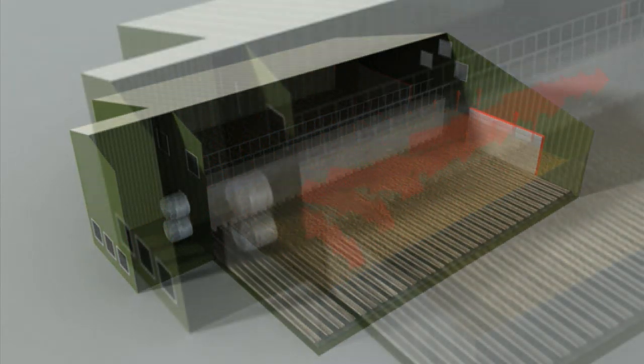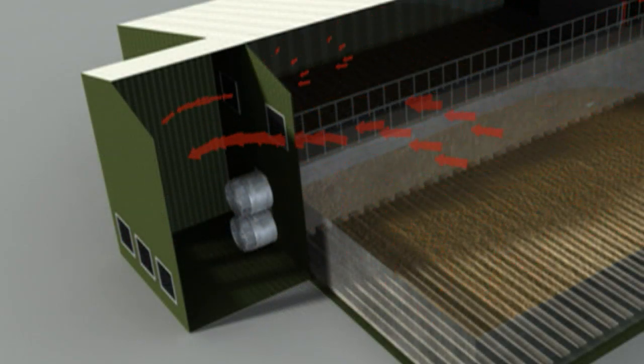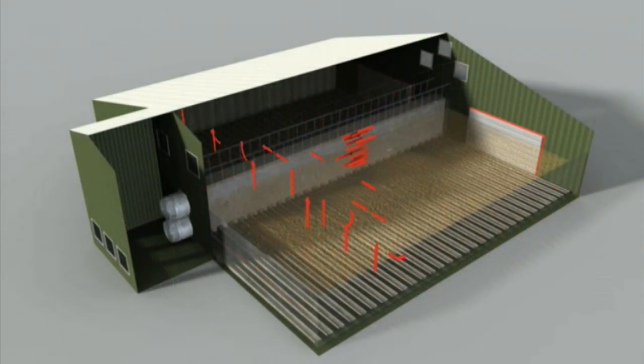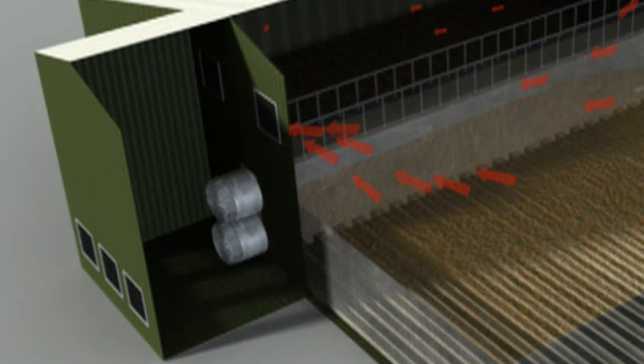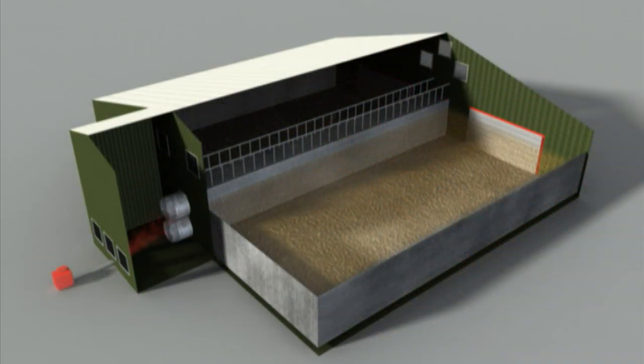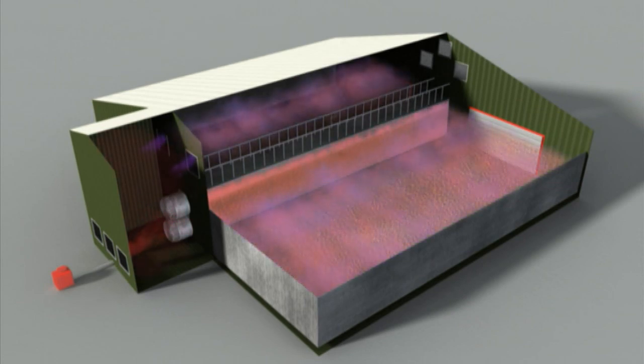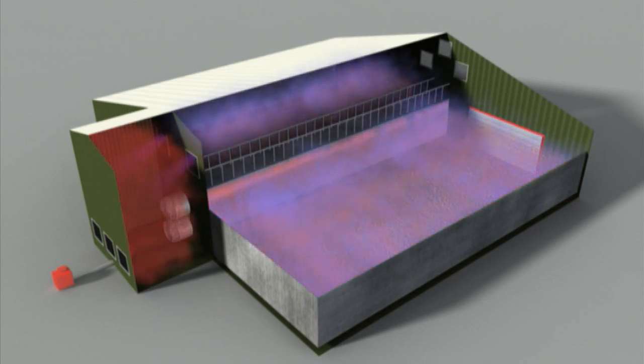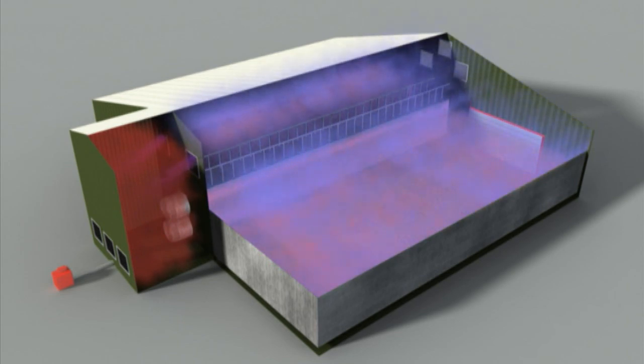Ensure the ambient louver is closed, the recirculation louver is open and the fan is on. Now air is delivered under the crop and at the same time is gently extracted from the store headspace and recirculated again and again through the crop. The fogger outlet duct is placed in the fan house and the fogging process begins. Because the ducts have been balanced with fans at low speed, on the basis of airspeed measurement, approximately equivalent doses of CIPC fog are delivered to the crop above each lateral.